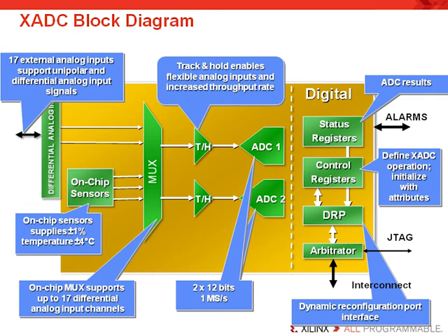The ADC conversion data is also accessible via the JTAG. In this case, users are not required to instantiate the XADC core. The dedicated interface uses the existing FPGA JTAG infrastructure, which can be directly accessed using the ChipScope tool. As discussed earlier, if the XADC is not instantiated into a design, the device operates in a predefined mode called the default mode, that monitors on-chip temperature and supply voltages.